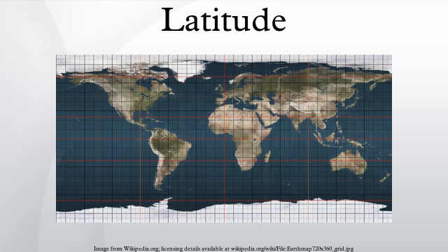No higher accuracy is appropriate for R since higher precision results necessitate an ellipsoid model. With this value for R, the meridian length of 1 degree of latitude on the sphere is 111.2 km or 69 miles. The length of 1 minute of latitude is 1.853 km, or 1.15 miles.